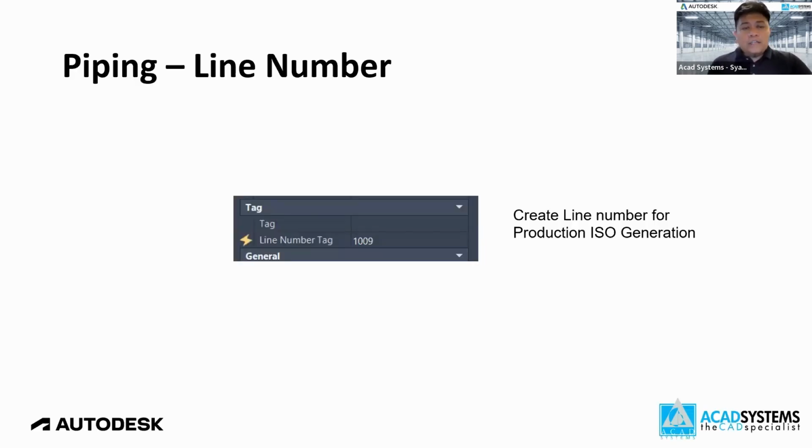Okay, so let's jump to the first objective before creating the isometric drawing. For every 3D piping, we need to specify the line number tag. In order to make the production ISO, we need to create the line number tag. If not, you are only able to do quick ISO. Later I will show the difference.